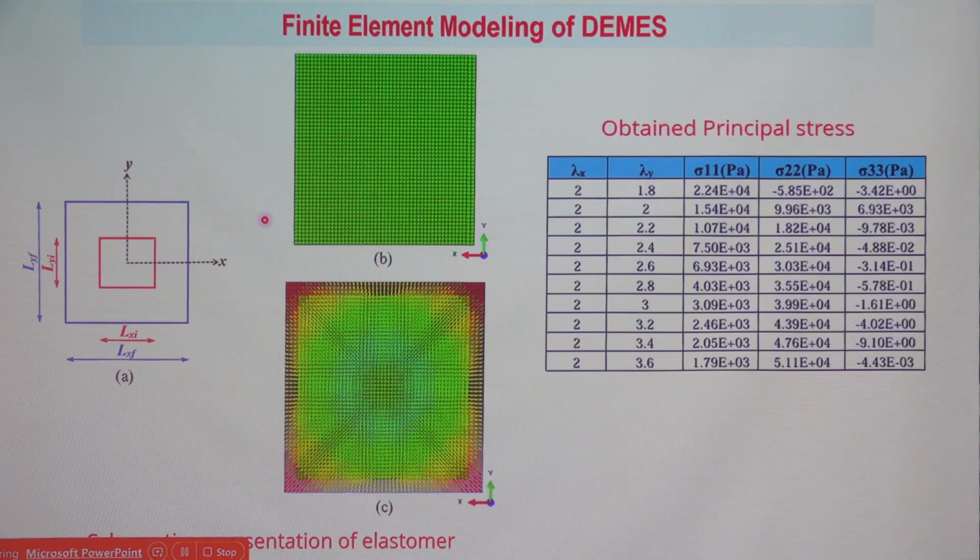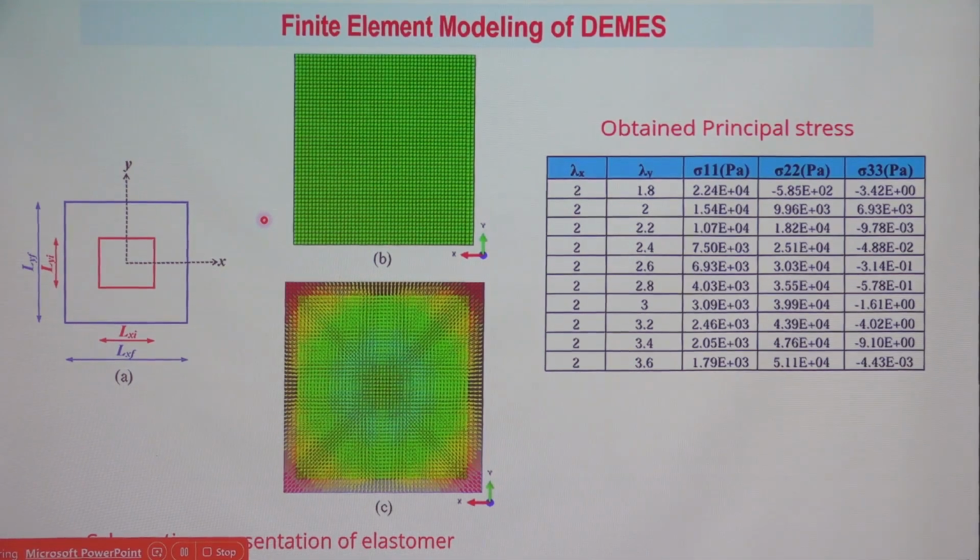So we are giving the displacement in x and y direction. We are saying that it will get displaced by 2.5 if you are giving biaxially in both the directions. So basically we are trying to give the pre-stretch of 1.5. You are getting my point? We are trying to change the dimension from 10 to 15. How can we do that?